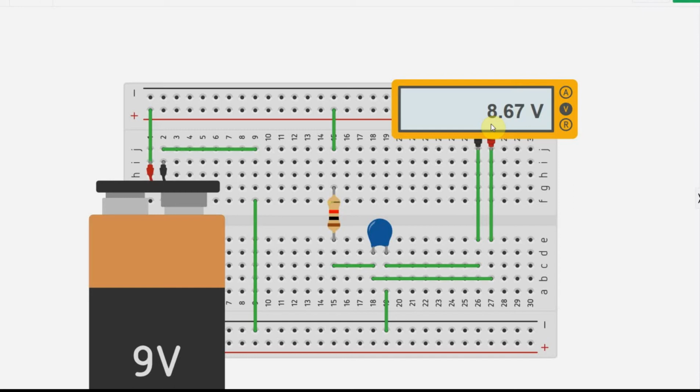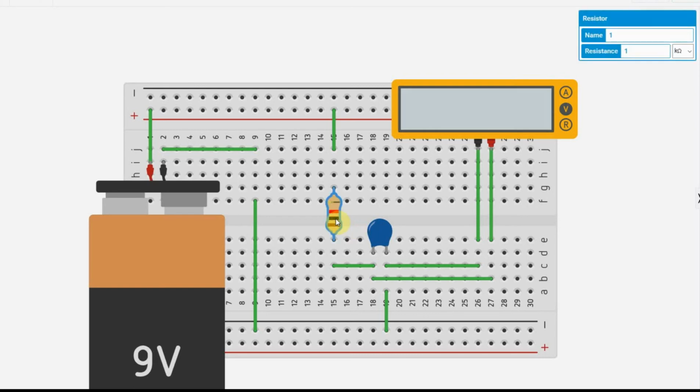We'll go over how to calculate in a later video. I just wanted to show you that that phenomena exists. I'm going to stop the simulation. I'm going to show you what happens if you change the value of this resistor down from 1K ohm to 500 ohms. By reducing the resistance, you increase the rate at which the capacitor charges.